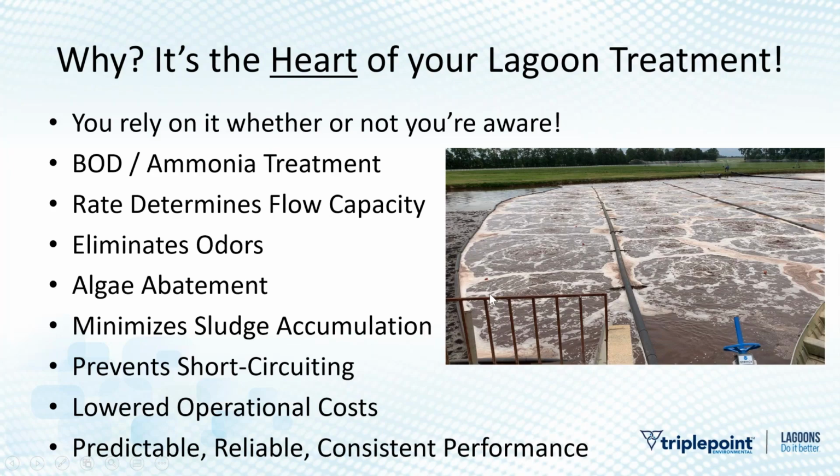But what we find is the more aeration you add, the more treatment you get. And that applies from a BOD standpoint, from an ammonia standpoint. In some cases, your lagoon may not be designed to handle the BOD or ammonia loading it's getting, or maybe it is designed, but you'll find later in the presentation that the more aeration we add, we can actually increase the treatment capacity in your existing lagoon.